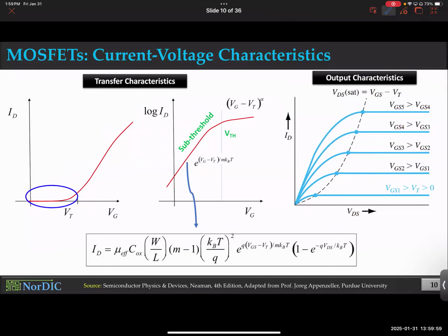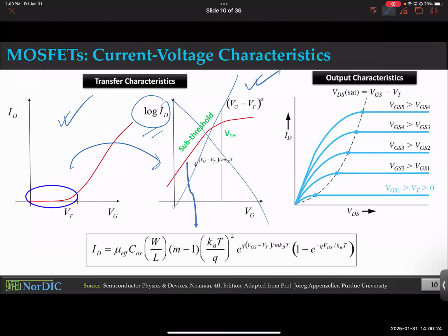So that's why when you plot them in semi-log scale, the same graph looks like this. So this is the better way of drawing ID-VG for VLSI transistors. Remember that, for the transistors that we use in our portable wearable devices, your computers, your cell phone. If you are a power electronics engineer, then you would probably never have to worry about this. Just care about this type of representation. If you want, you can plot it, but that's not going to make any difference at all.